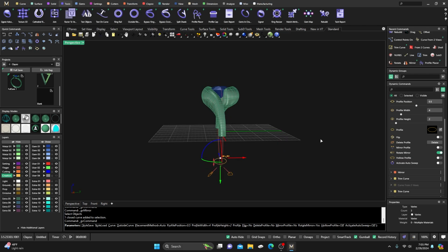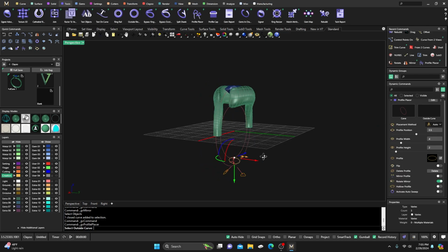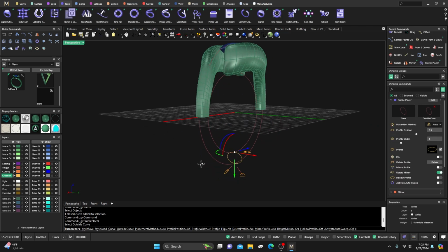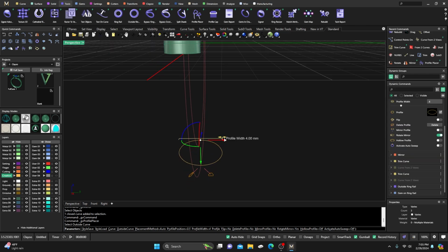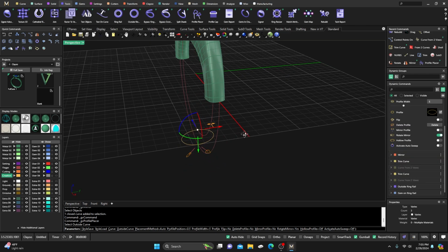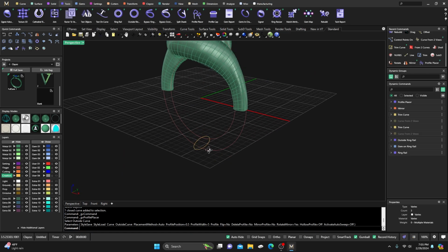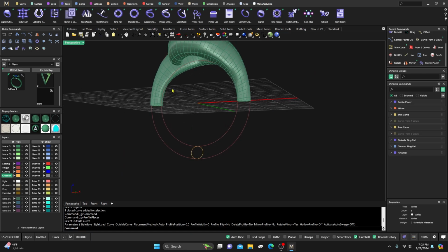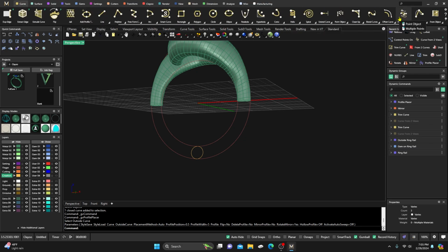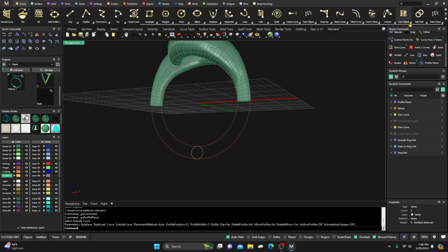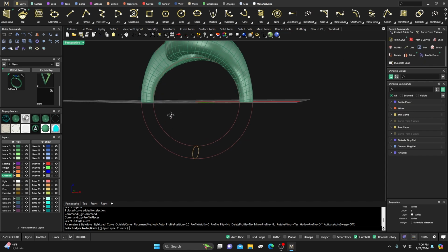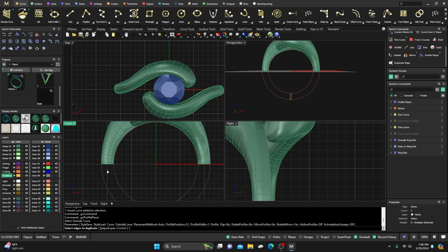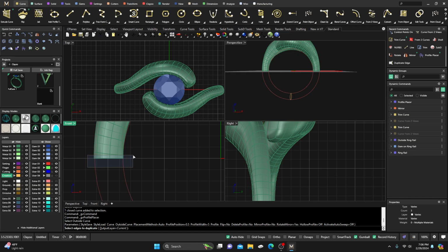And of course we want to give it to our other rail, our outside ring rail, and we want to give it a little bit more style, so we're going to bump that out a little bit to 5, and we'll hit enter, and we can always go back and change that, right? And now what we need to do is go to our curves, go down and go to our from object, and we want to duplicate edges, so we'll just go to our front view here, and we'll just select those there.